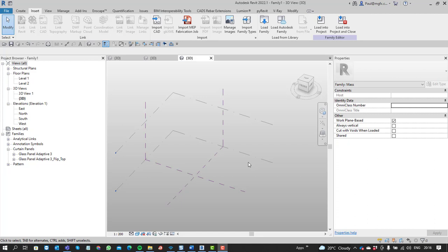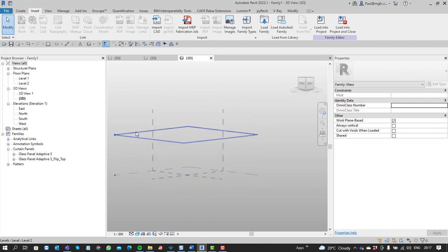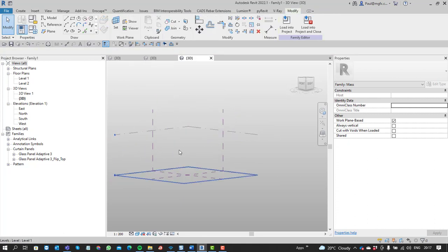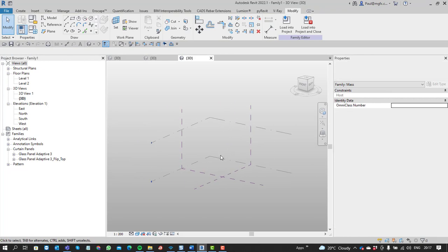that it didn't. So in this case I'm now also wanting to differentiate between why you would want to choose to model something in place, or why it would be better to model something within a family. And to illustrate that, I'm also going to use the loft in this family. So I just created two levels. One is at 40 meters, the other one is at 0, to be the same as the other two examples.